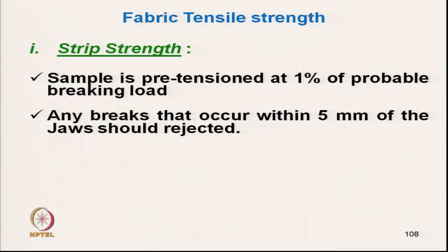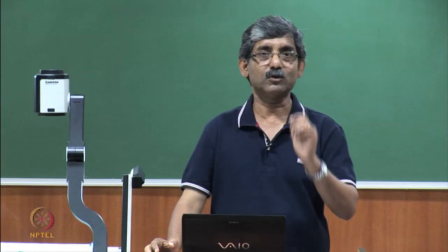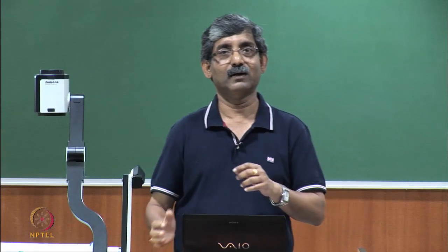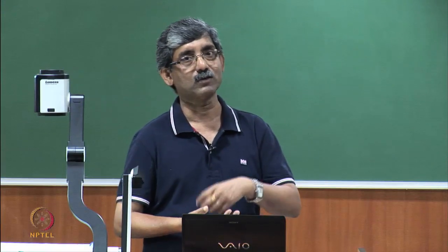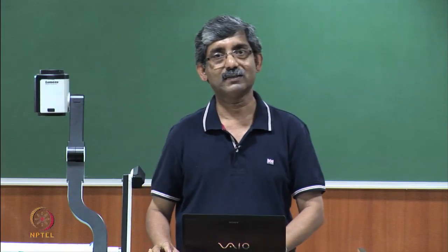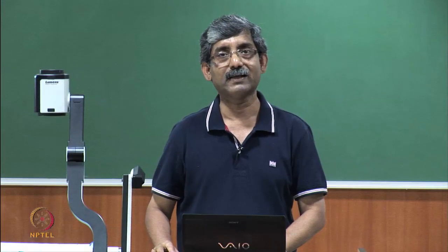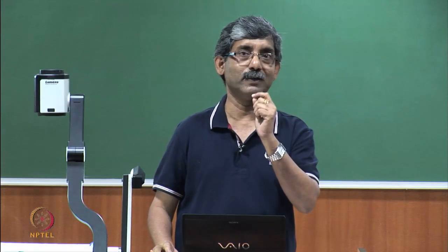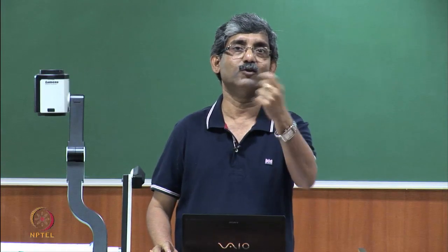So, suppose the jaw pressure is very high, in that case there may be some jaw breakage. So, those fabrics we have to reject. Okay. Either there may be jaw breakage or maybe jaw slippage also. So, in that case any breaks that occur within 5 millimeter of the jaw should be rejected. That means within 5 millimeter means that it had occurred within the jaw, after that it has come out, okay,